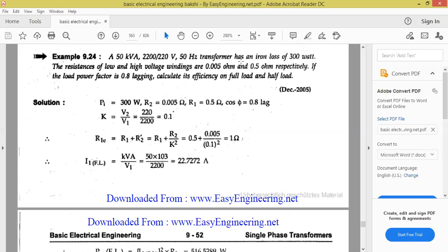So you can convert the resistances to primary. So resistance referred to primary, R01 equal to, so what is resistance? Primary winding R1, R2 they have given. You can directly use them separately, but this is the standard method. Convert this resistance to R02 or R01. R01 I am converting, R1 plus R2 dash, substitute, any problem.